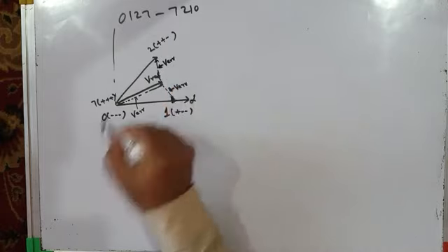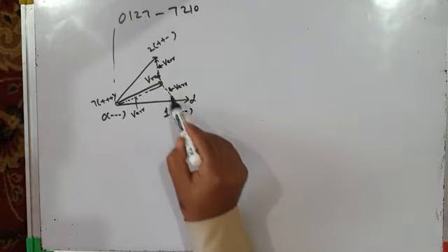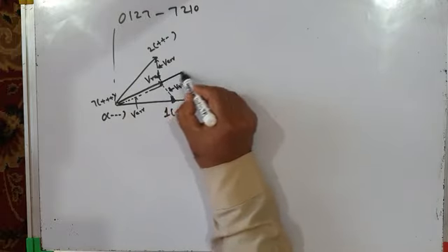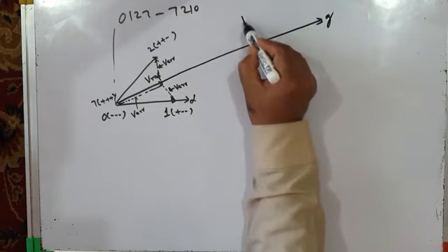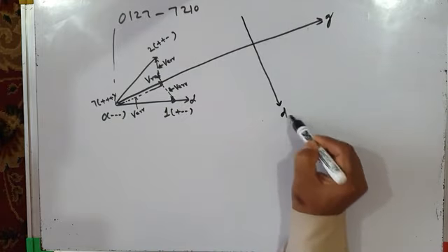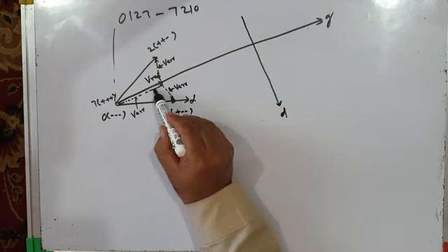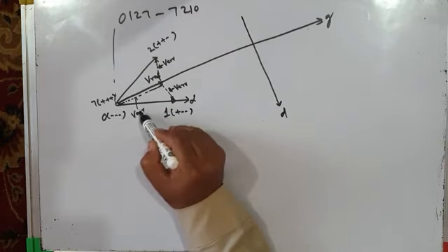And when we integrate these error voltage vectors, this gives the stator flux ripple, along the D and Q axes. You already know this is your Q axis, this will be D axis. It gives something like this. First of all, we integrate this error voltage vector when null vector 0 is applied.